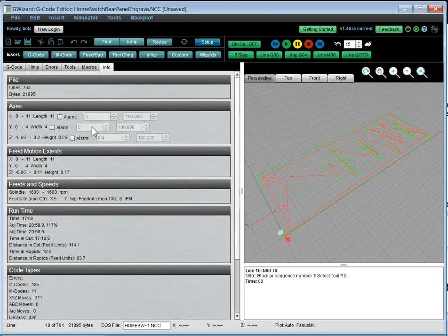You might have a 4th axis set up where you don't want to go too far left or right, depending on which axis it's aligned with, or you might run your tool right into your 4th axis. So that's a really useful feature to help you flag potential problems.